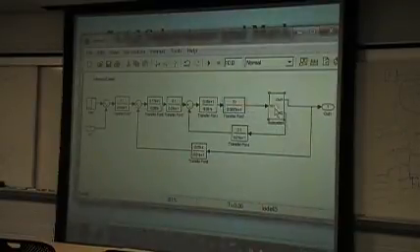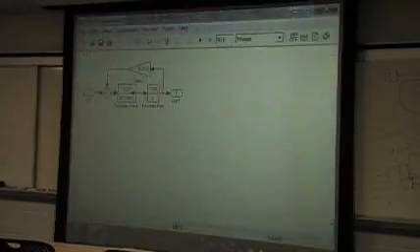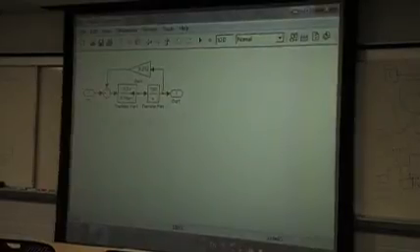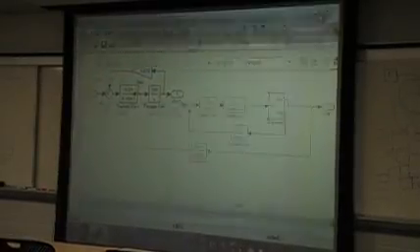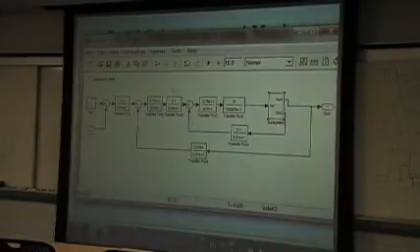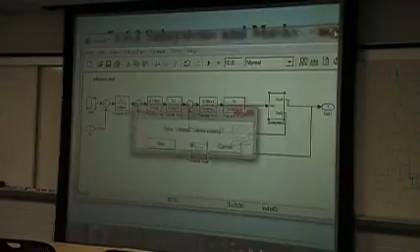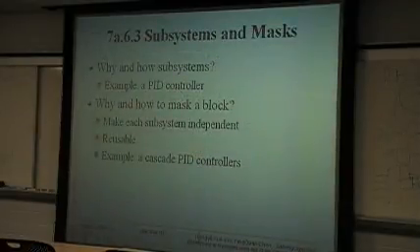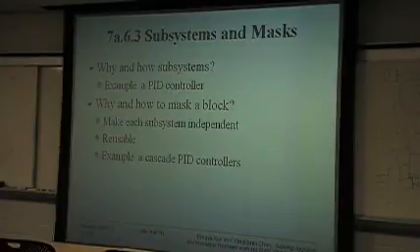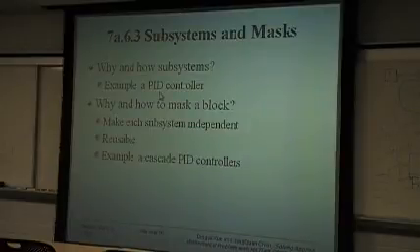If you double click it, it will display the components in the subsystem. In this way, you can simplify the structure of the simulated model. So this is why we need subsystems to extract models. In this way, we can also create blocks such as a PID controller, as one block, a subsystem.